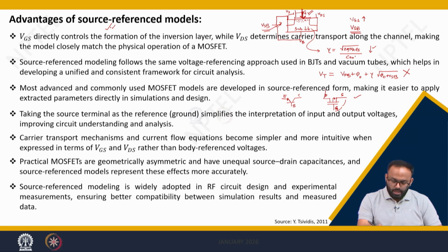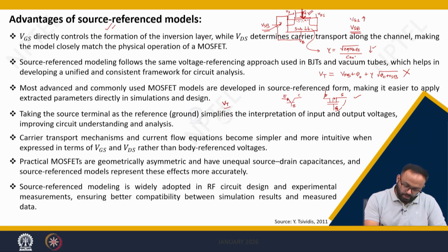model, we saw that the Vt term, the threshold voltage term, is coming automatically in the equation, right, we need not bother about it. However, Vtb is not coming up. That is what the equation captured in the source reference model as (Vgs minus Vt) whole square, or you can say (Vgs minus Vt) Vds minus alpha into Vds square divided by 2, correct, into W divided by L into mu into Cox.